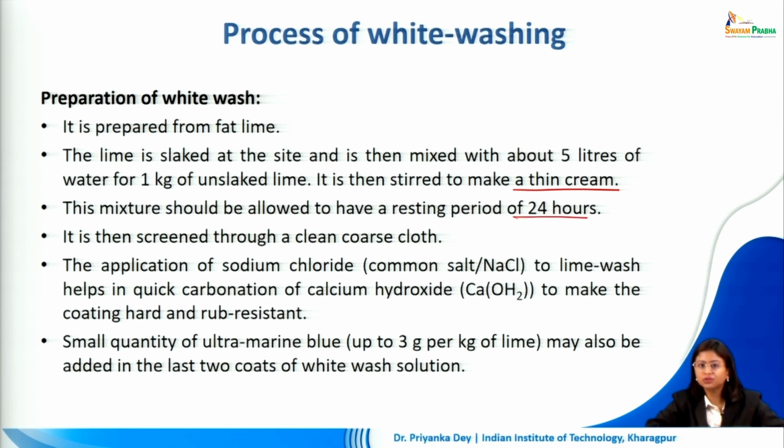It is then screened through a coarse cloth to ensure that no debris remain. We do not want an uneven finish. The application of sodium chloride to lime wash helps in the quick carbonation of calcium hydroxide to make the coating hard and resistant. Small quantity of ultramarine blue up to about 3 grams per kg of lime may also be added in the last 2 coats of the whitewash solution.